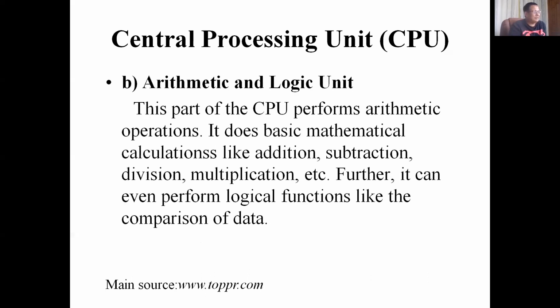Next is the arithmetic logic unit. We have discussed this before. Earlier, we discussed the arithmetic logic unit as an adder subtractor. It's sometimes called the ALU. It's a circuit made of XOR gates and AND gates in order to perform the sum and carry, and thereby being able to add or subtract nibbles, bytes, and words.